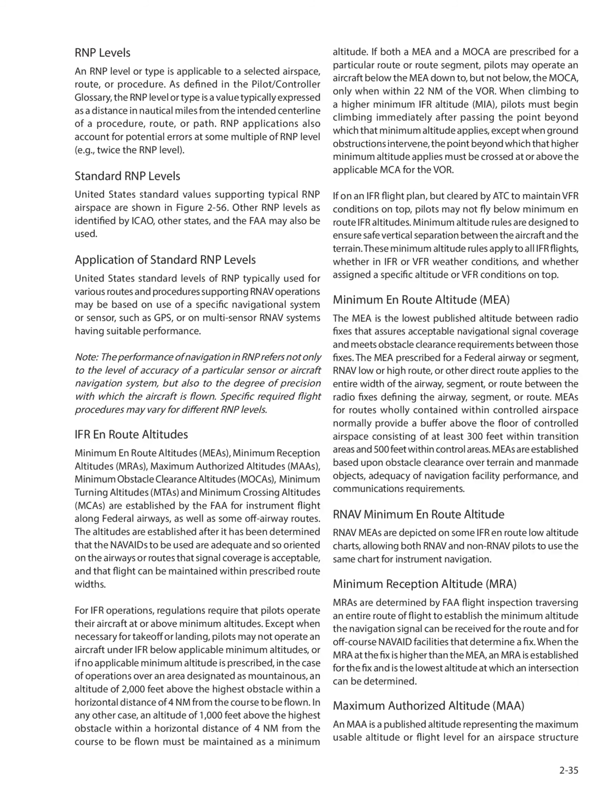RNP levels. An RNP level or type is applicable to a selected airspace, route, or procedure. As defined in the Pilot/Controller Glossary, the RNP level or type is a value typically expressed as a distance in nautical miles from the intended centerline of a procedure, route, or path. RNP applications also account for potential errors at some multiple of RNP level, for example, twice the RNP level. Standard RNP levels. United States standard values supporting typical RNP airspace are shown in Figure 256. Other RNP levels as identified by ICAO, other states, and the FAA may also be used.